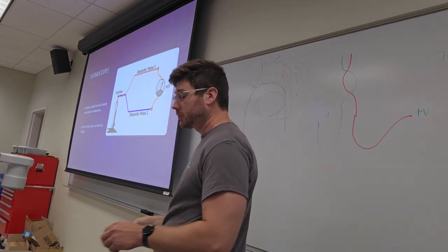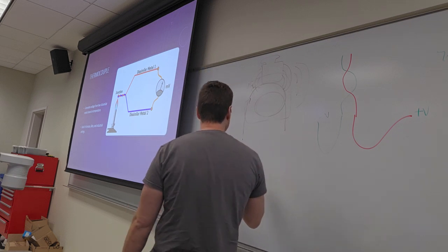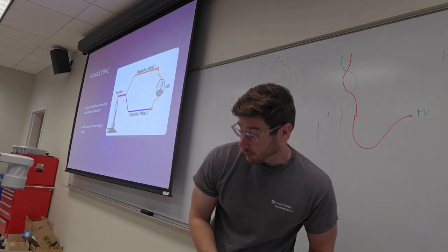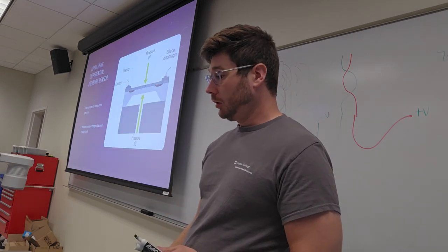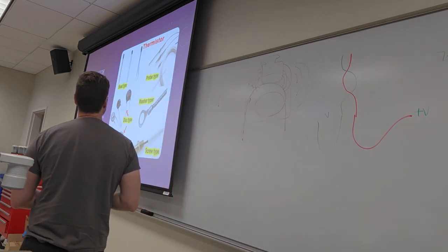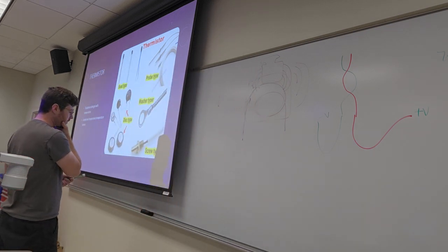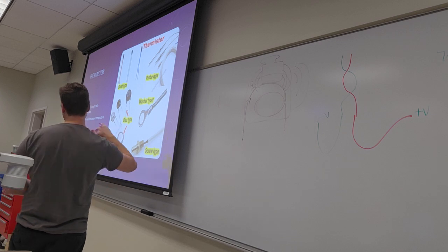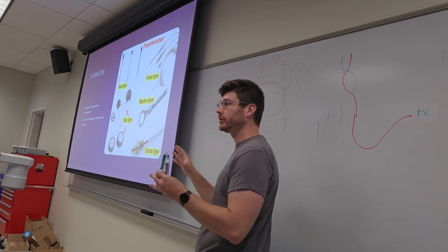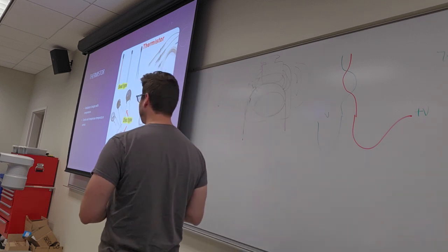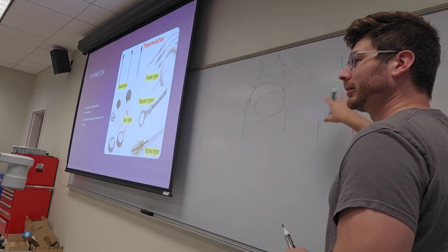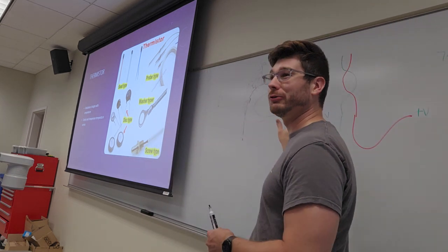Thermistors are different. Thermistors are inside of 3D printer heads. They're inside of a lot of things that need really fast, relatively low temperature heating monitoring, like 200 degrees Celsius-ish. Much above that is a little bit too high. But for an oven, you probably want a thermocouple, again, like 500 degrees rather than 200 degrees.